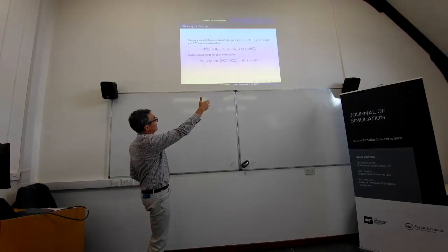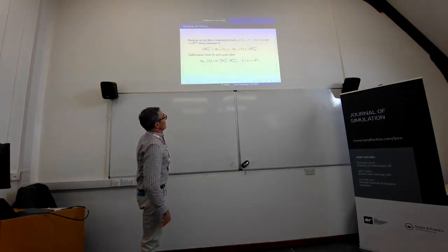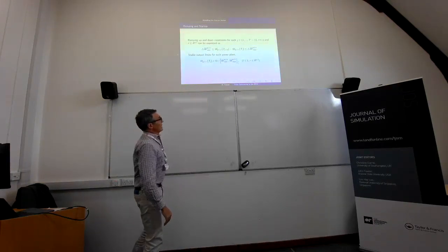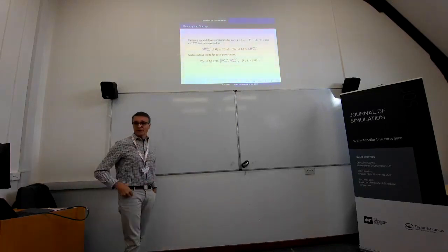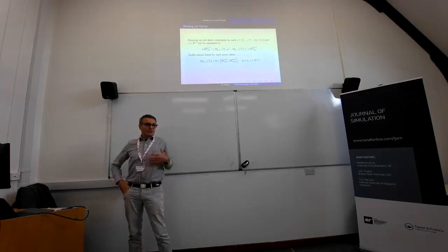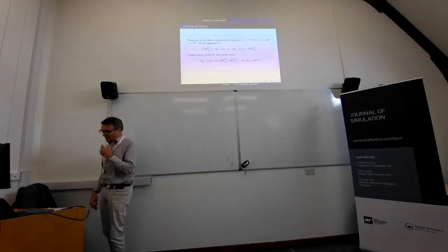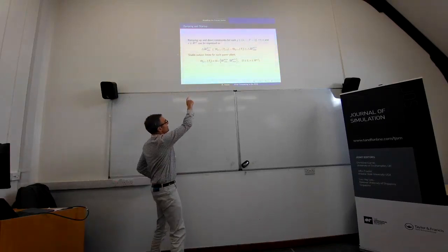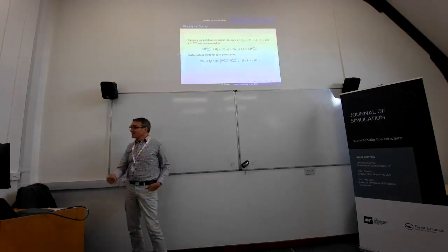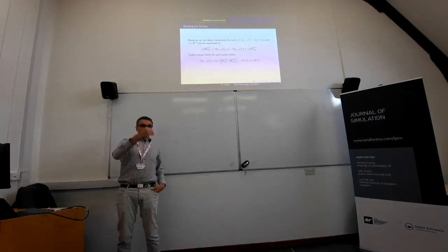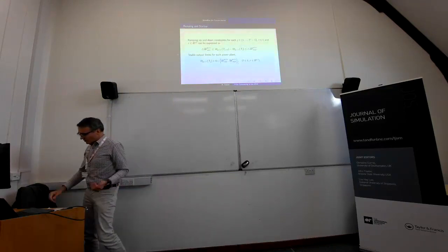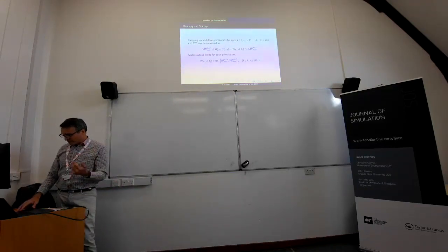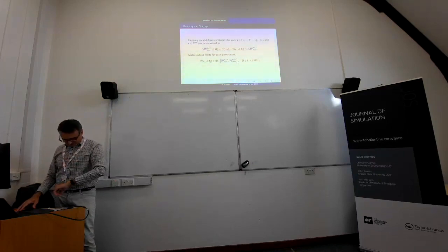So there's clearly an upper bound on how much power a power plant can deliver, but there's also a lower bound below which it's just not economical to run. And this then introduces basically binary variables, because you either deliver at least this much power or you don't deliver at all. So that then introduces big-M type constraints.